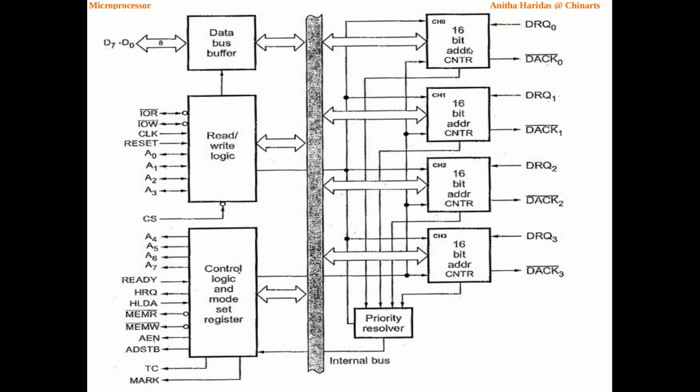Who will be writing these values? It is the duty of the CPU. Now how will the CPU write it to the corresponding channels? It will be sending the values on A0 to A3. Imagine the CPU wants to activate the input output device connected to channel 2. It has to first write the address in the address register, and the count in the counter register.